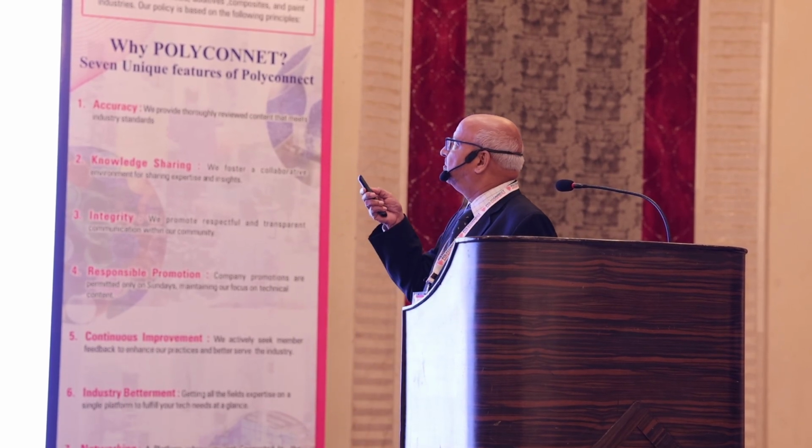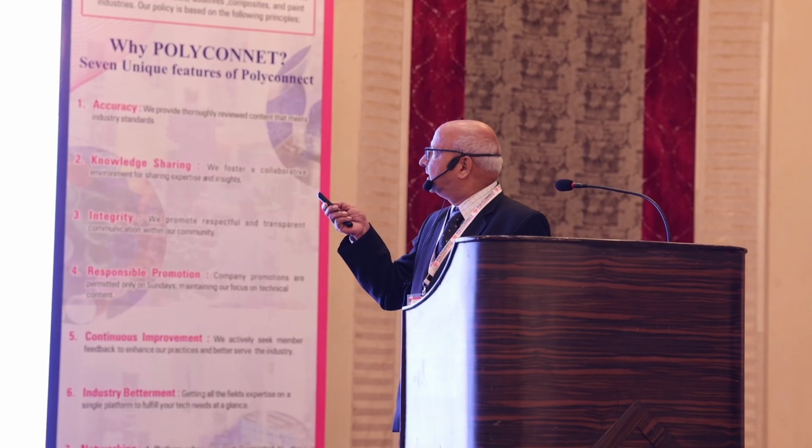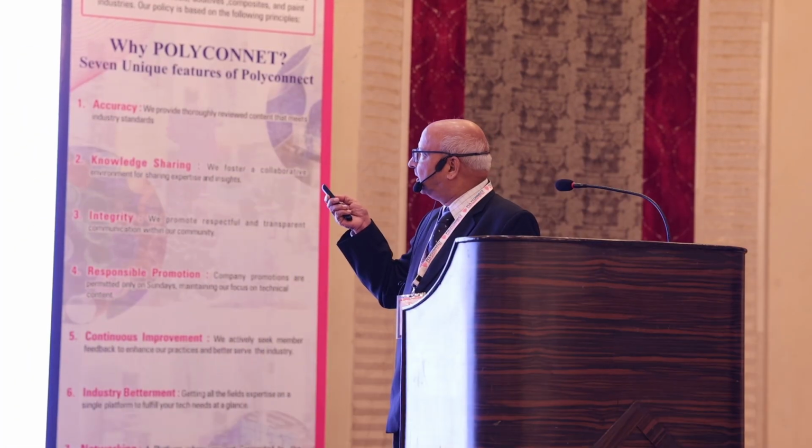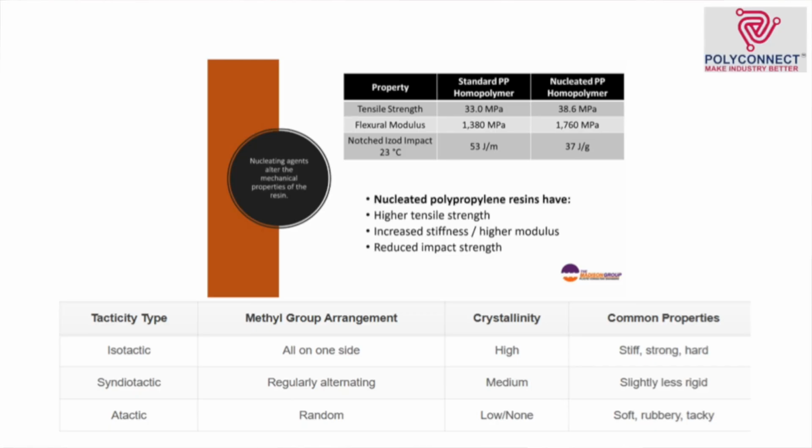So in polypropylene you have fillers, rubber blending, reinforcements like fibrous materials, and clarifying agents to improve the clarity, which we need in the food packaging industry, where the heat property and the clarity are very important. Here is a comparison between the standard polymer and the modified polymer, where a nucleating agent is added, which also improves the clarity of the polymer.